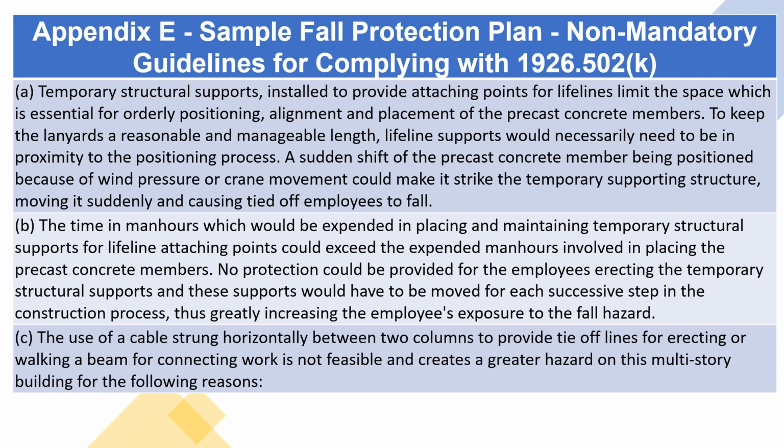B. The time and man-hours which would be expended in placing and maintaining temporary structural supports for lifeline attaching points could exceed the expended man-hours involved in placing the precast concrete members. No protection could be provided for the employees erecting the temporary structural supports, and these supports would have to be moved for each successive step in the construction process, thus greatly increasing the employee's exposure to the fall hazard.